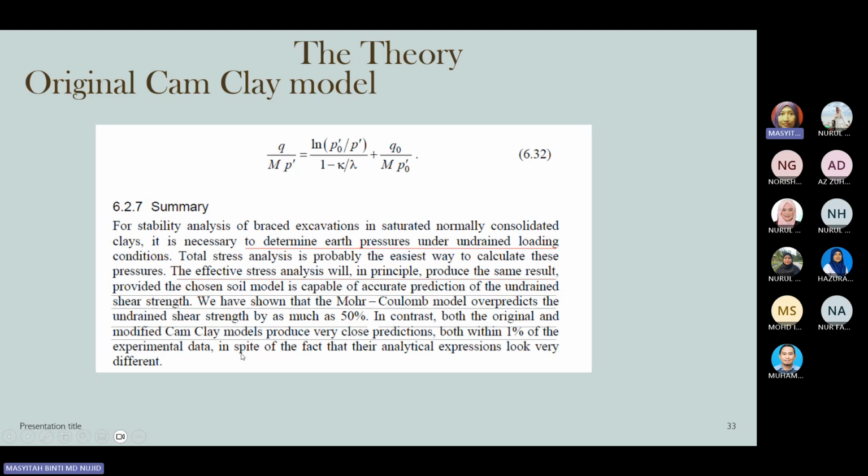Yes, it is true, because some geotechnical engineers or practitioners are afraid to use advanced constitutive models such as original Cam-clay or any kind of model because it's difficult to find the correct values of these parameters. For example, you want to get the parameter lambda, the parameter kappa, and then you want to find exactly the calculations to estimate the void ratio at the final, initial, or void ratio at every stage of the applied pressure.